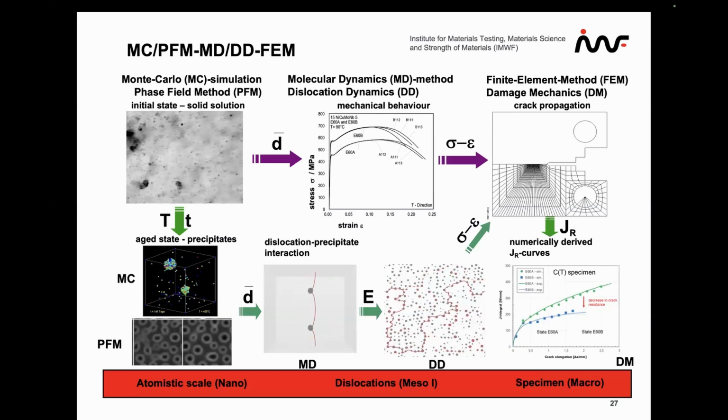With phase field modeling, we can handle the larger precipitates, and then the interaction of a dislocation with such precipitates of individual size was done in order to get some energies which are needed for dislocation dynamics at the interface between larger and smaller particles, interacting with running dislocations in the material under deformation analysis, and coming out with stress strain behavior with particle arrangements of different sizes, and then following this way to derive J integral values.